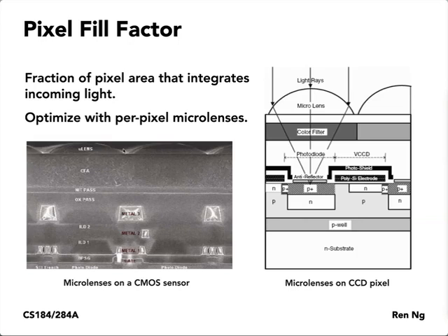And so as to the question that's asked, do the microlenses straighten light rays out to be normal with the pixel size? Sort of, yes, but I think a more intuitive way to think about it is the microlens is here to take light that's coming from the main lens, arriving at this surface down here, which is the top of the sensor, and then focus it down into the photodiode area to try to avoid these metal layers.